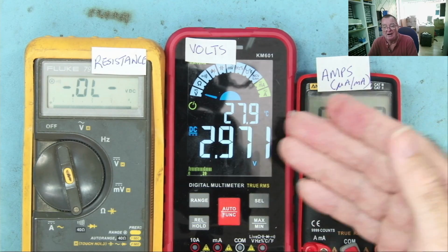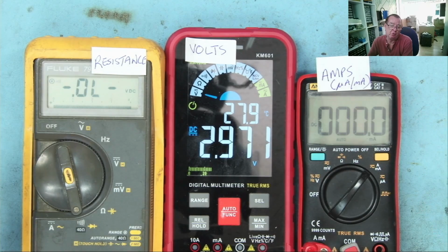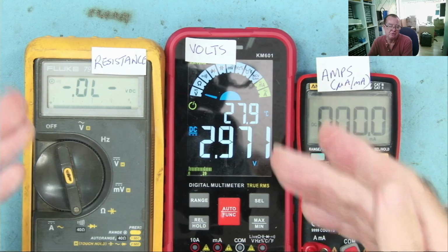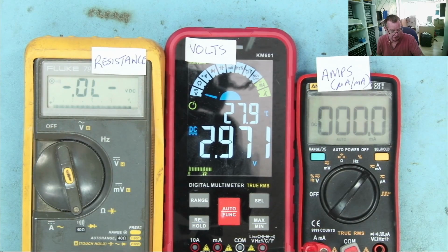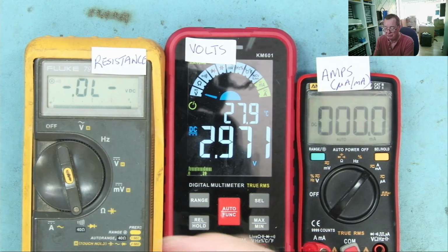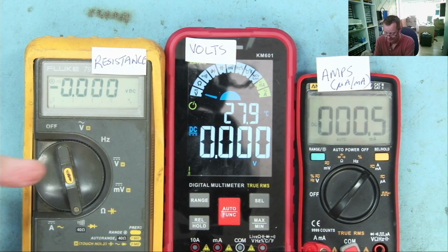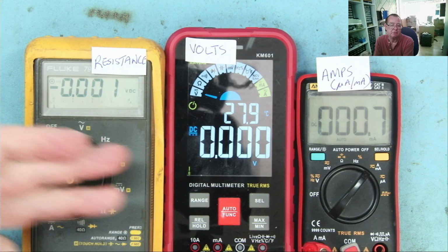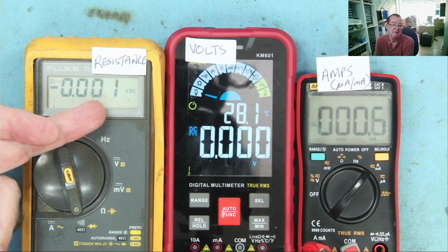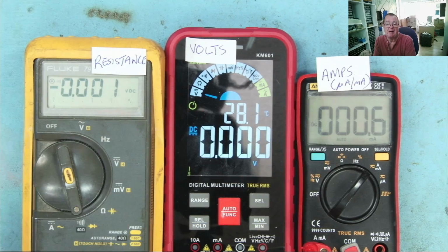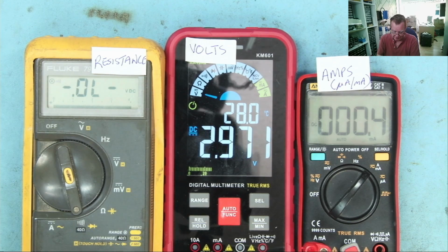That's why diodes, although they effectively conduct, they're like a short in one direction, don't show up on the resistance range, because 0.1 volts is not enough to turn on the diode or transistor junction. Let's short the leads together. And you will see the meter is now generating basically 0 volts or very close to it. It's telling us effectively just short, 0 volts. And it's passing about 600, 700 microamps. Yeah, 0.6, 0.7 milliamps into the short. So that's the current going into the short.